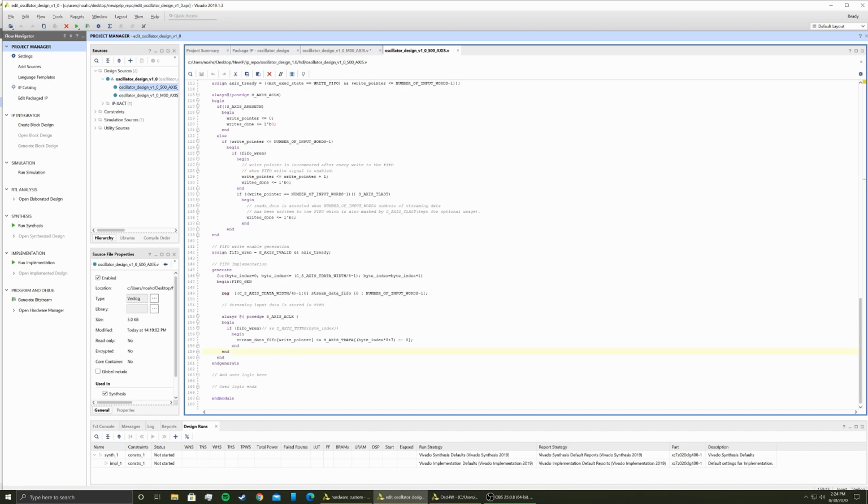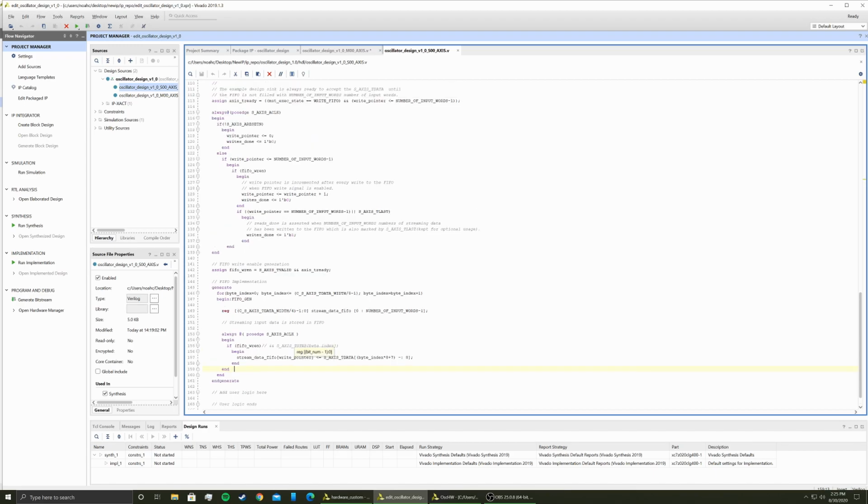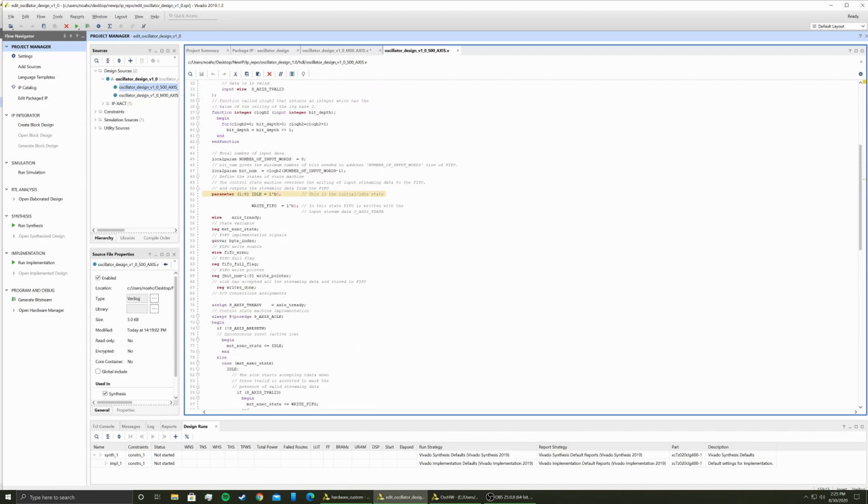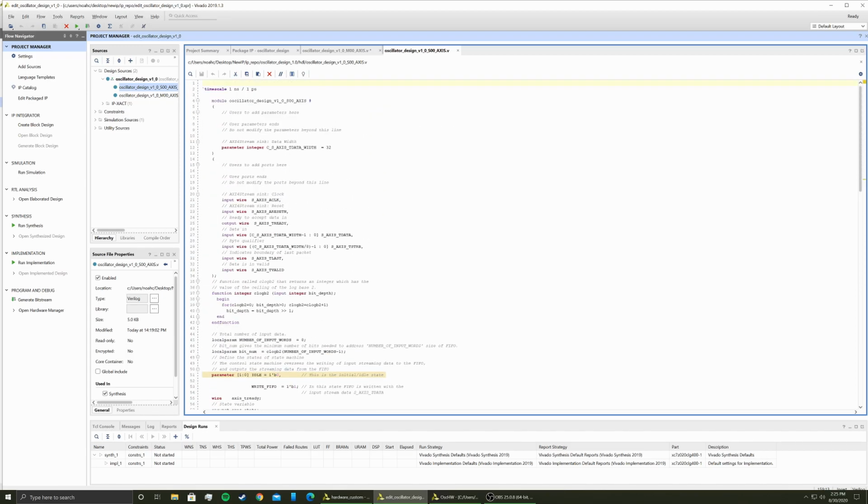This will automatically grab data from whatever you're sending, in this case the Zynq 7 system, and whatever you call it to send. So it's typically not something you have to worry about, but if you would like to mess with the FIFO built in within the slave AXI, you can do so. I would not recommend it, but it's there for your discretion.